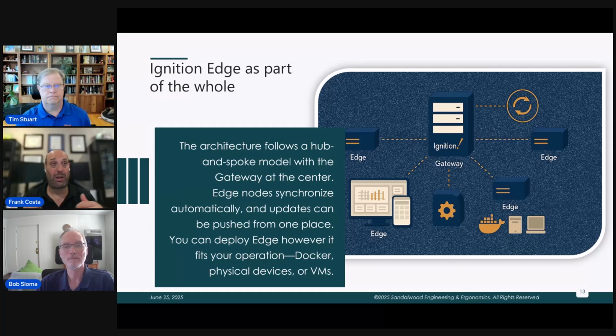Again, as I alluded to, there are containerized versions of this, which means you don't have to buy an appliance. If you've got a Wago PLC that supports it, you can go ahead and deploy Ignition Edge on it. If you've got a Phoenix Contact PLC, you can deploy Ignition Edge right on the hardware, and it's designed to do that. Some of these are what they're calling soft PLCs, 4-core processors, one dedicated to PLC work, allowing the other 3 to use these Edge services.